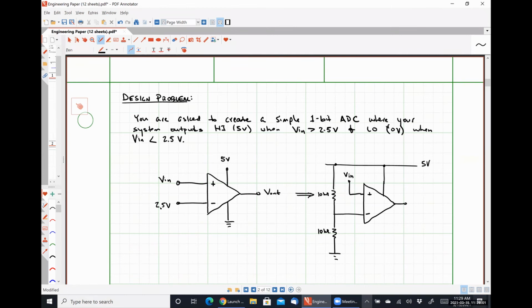And they're also significantly larger than the output resistance so that when we use them to load things, we don't see a significant voltage drop over the internal output resistance. So kilo ohm size resistors are really the sweet spot for biasing op amp circuits, okay? So in all of your designs and all that kind of good stuff that I'm going to ask you to do, where it's up to you to decide what component values, things are just generically going to work significantly better if you choose to use kilo ohm size resistors for all of your biasing circuitry, okay?